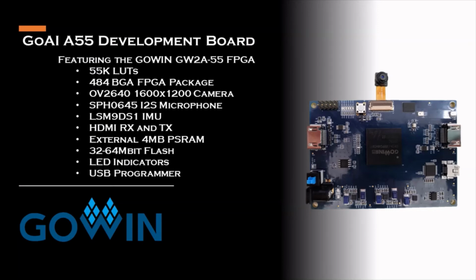Lastly, we have the Go AI GW2A55 development board. This board uses a 55K lookup table FPGA. This device does not have the embedded PSRAM and instead uses an external Cypress HyperRAM part. This is just to show another option. The reason is this is a bigger FPGA. You may want to use external memory like DDR or external HyperRAM, multiple HyperRAMs. And so it's just showing a different option.